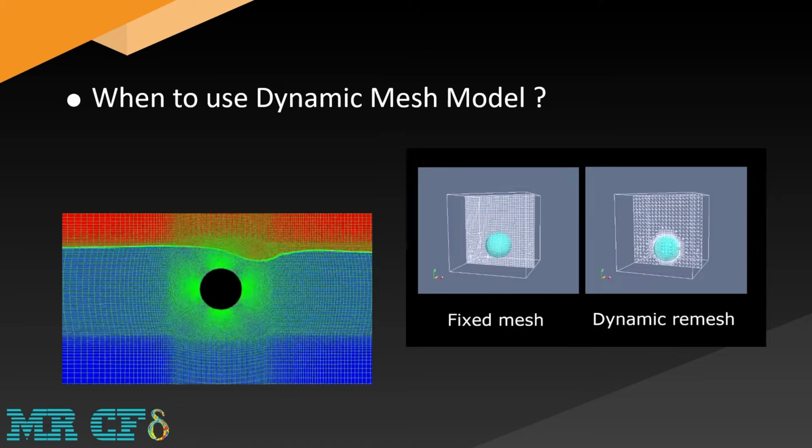For example, a certain boundary has rotational or translational motion. This rotational or translational movement causes the meshing in the area around its moving boundary to undergo deformations at the same time. In such cases, we should employ the dynamic mesh method to provide the software with the ability to change the mesh grid of the computational area over time.